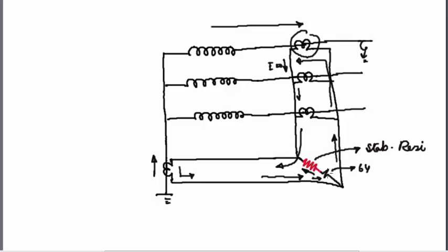Now apart from this REF relay, there are certain places where we introduce one more relay at this point, and this relay is called the SEF relay, also called the standby earth fault relay, which is used to provide protection against persisting faults in the system. So this was all about the REF protection of transformers. Well, in the next video we shall see the calculation of the stabilizing resistance needed for high impedance REF protection.